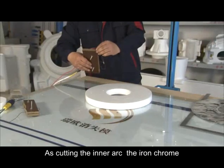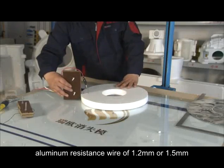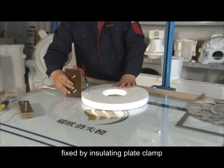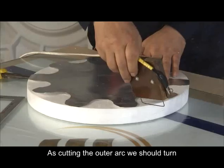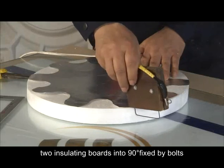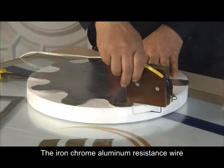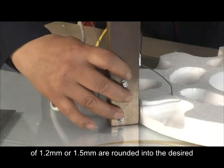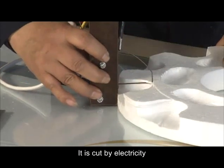When cutting the inner arc, the iron chrome aluminum resistance wire of 1.2 mm or 1.5 mm is rounded into the desired inner arc. Fixed by an insulating plate clamp, it is cut by electricity. When cutting the outer arc, we should turn two insulating boards into 90 degrees fixed by bolts. The iron chrome aluminum resistance wire of 1.2 mm or 1.5 mm is rounded into the desired outer arc fixed by an insulating plate clamp. It is cut by electricity.